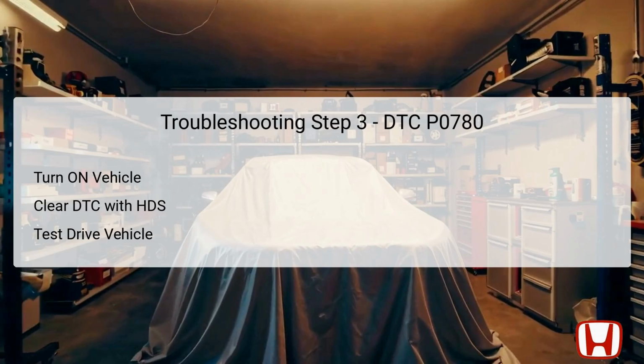Once the vehicle has reached 37 miles per hour, the technician should bring it to a stop and then accelerate from a stop at full throttle to ensure a thorough check of the shift response.